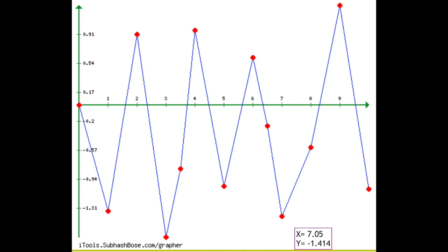However, there can be some deviation in why our calculations were slightly off. Sometimes it would reach up to 1.4 Gs, for example. One reason could be that the screw didn't perfectly fit in the structure, which could result in a bit of swinging and a bit more vertical movement than horizontal, which would change the amount of movement of the structure. Also, with the Arduino, we attached a sensor to the very end of the portion that moves horizontally, and since it wasn't closer to the center, there's potential that the results could have been slightly skewed.